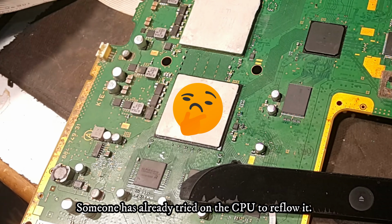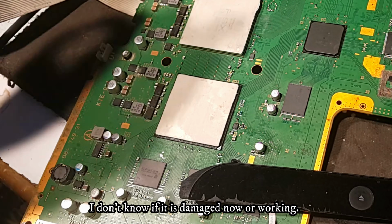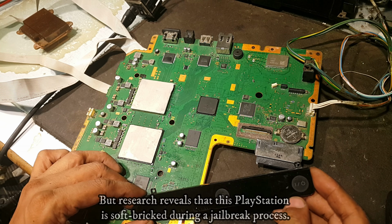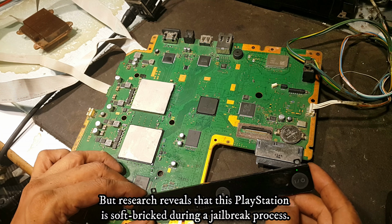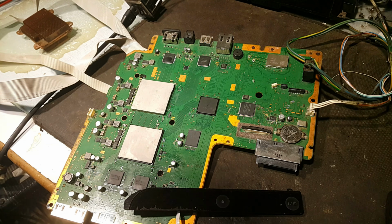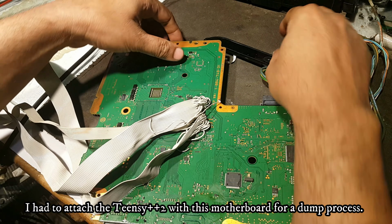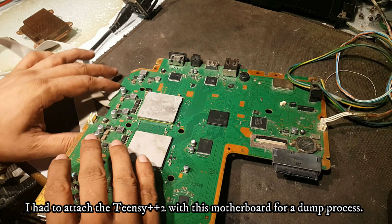Someone has already tried to reflow the CPU. I don't know if it is damaged now or working, but research reveals that this PlayStation is soft bricked during a jailbreak process. As the NOR flasher was not showing its ability, I had to attach the Teensy++ 2 to this motherboard for a dump process.